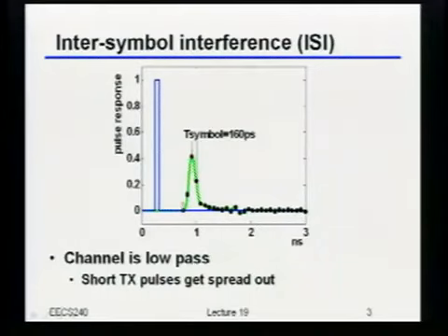So, you can see this thing basically got spread out due to the low-pass filter. You can actually see there's also some other weird, funny-looking stuff. There are these little ripply things going on over here. Anybody have an idea what those little ripply things are coming from, physically? Yeah, those are reflections, right?